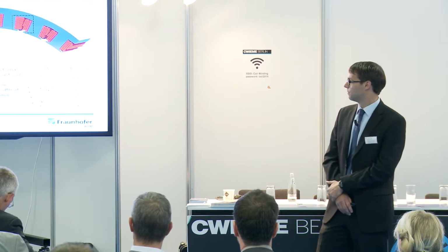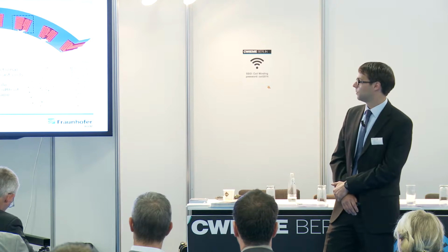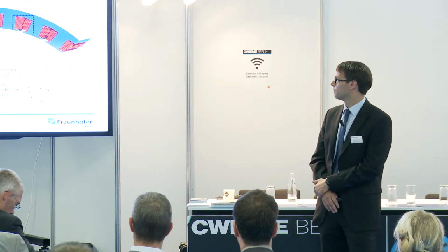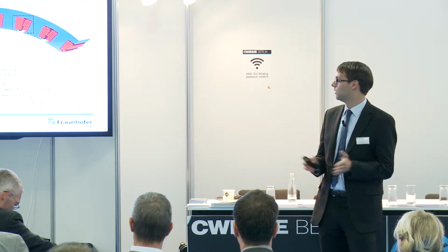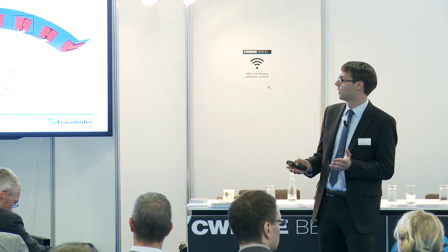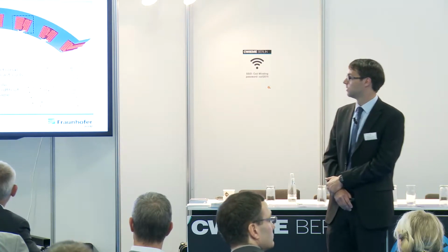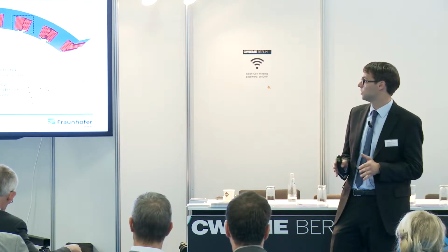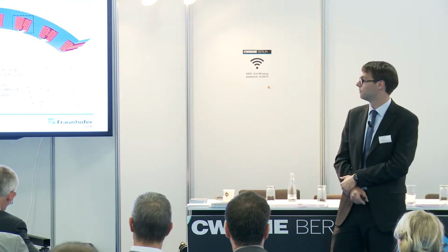And further advantages from the geometrical side are that we can realize innovative cooling concepts. Perhaps we can increase the length of the end windings to reduce thermal hotspots, or we can integrate cooling channels in the conductors. So with the casting process, we have very good geometrical flexibility in the coils.